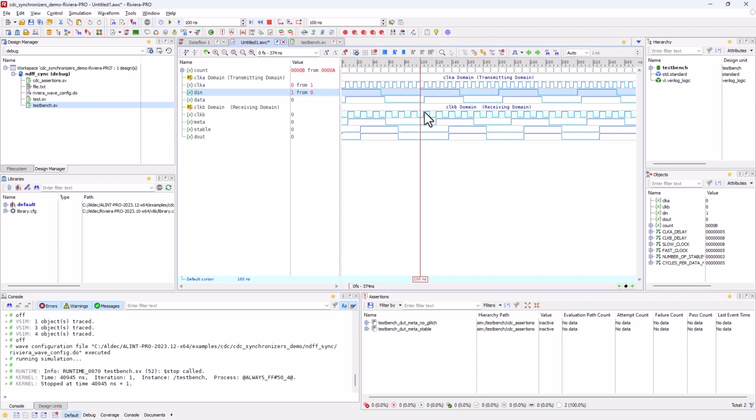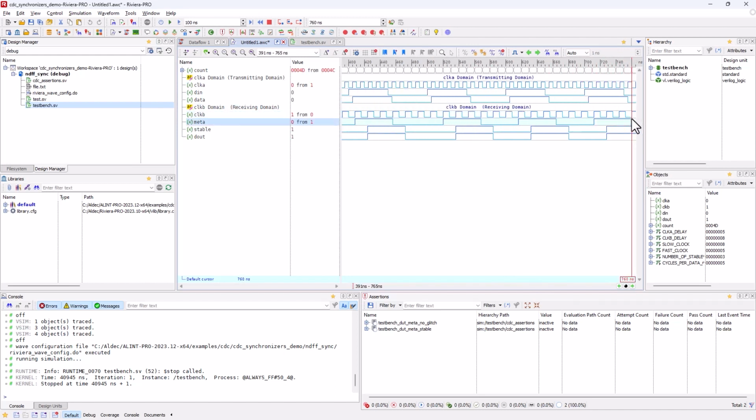So in this case, we have dn being on. Here's the first clock edge, from here to here, and the second clock period. And so this dn signal is stable for that entire clock period. You'll notice the exact same thing applies over here. Both turn on at this exact moment, stable for 1, 2, and even 3 clock cycles in this case. And that continues on with the rest of this simulation.